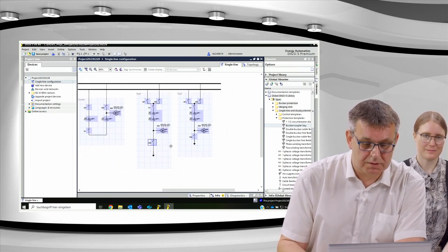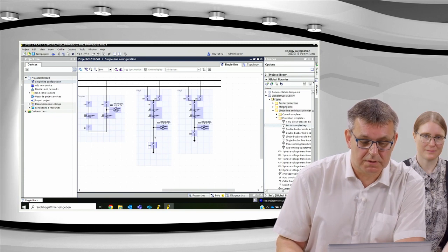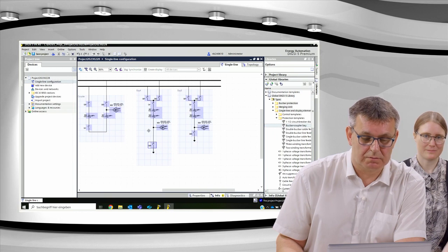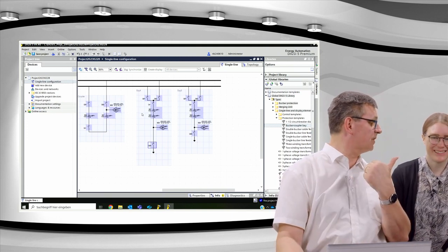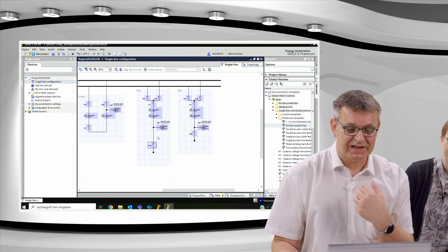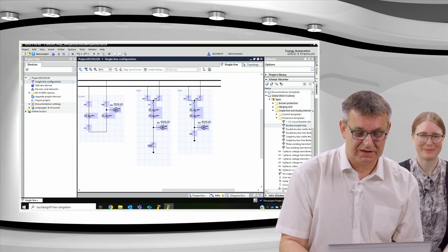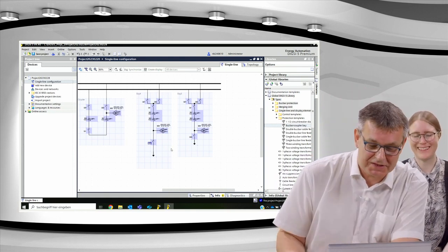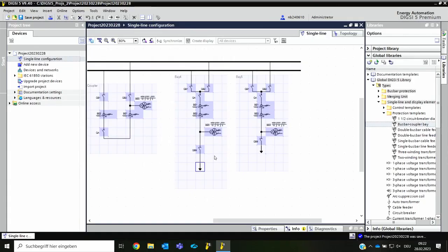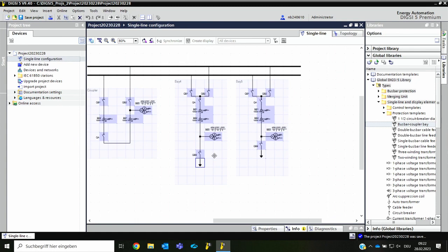Let's shift a little bit. They are line side, neither. No, both CTs are line side. Do you want to change the other ones to busbar side? I think I did it, yes. Okay. Shall I change it just to leave it busbar side? Okay. So now I was a little bit confused, sorry. Because now I mentioned it's already line side. Both of these current transformers are line side.